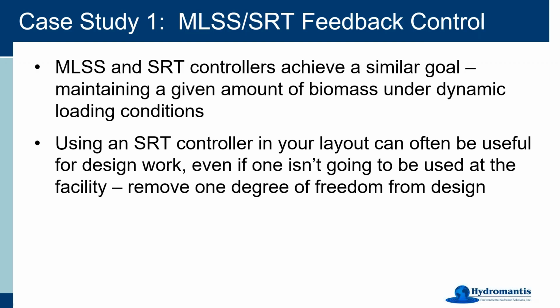Meanwhile, I'm moving other things around. I'm changing tank sizes, I'm changing aeration setups, clarifiers and so on. But I can always make sure that I'm going to waste the correct amount for whatever size I have by using an SRT controller, not for process control, but just to have one less degree of freedom to worry about.